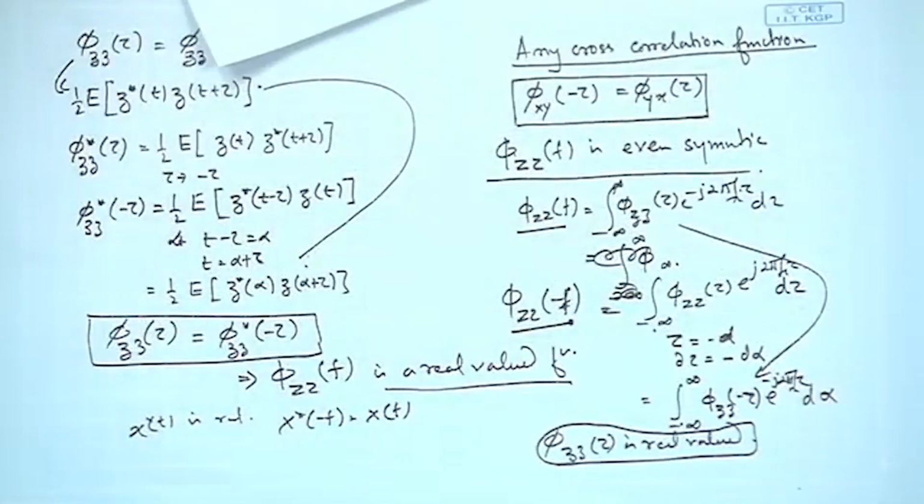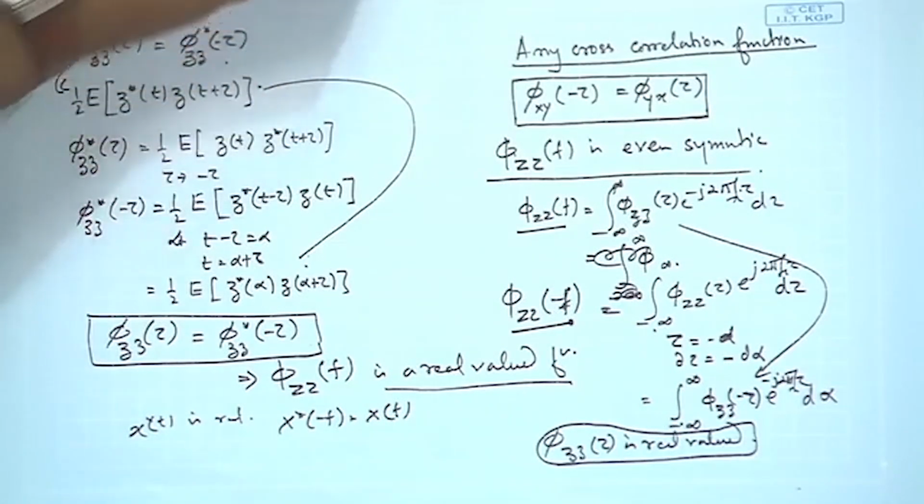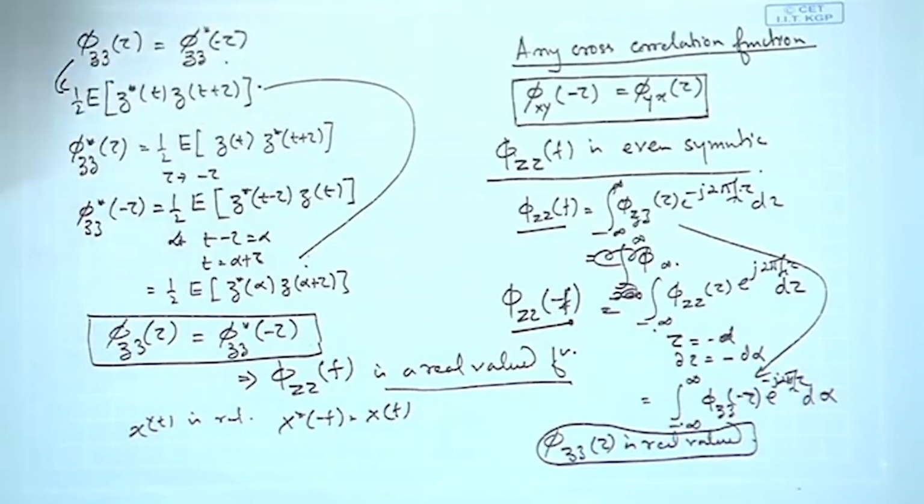Also, there is sometimes a reference to whether you are considering one sided or two sided. If you are considering one sided noise spectral density, it will be N naught. If you are considering two sided, it is N naught by 2. So, accordingly you should set all your expressions properly. The next thing that we are interested in is the signal space representation.